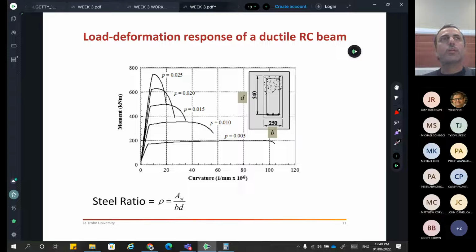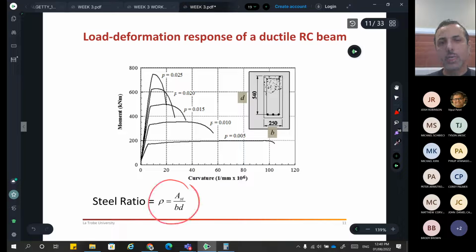It's just a message telling you that we need to design our reinforced concrete sections to be with adequate ductility. We want it to flex, to give us warning, right? And with experience from standards, they're always going to tell you the good ductility level in terms of steel ratio is defined when the steel ratio is actually just about this figure here, because you see it's giving us warning.